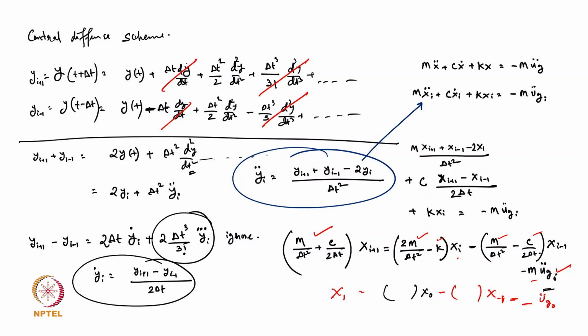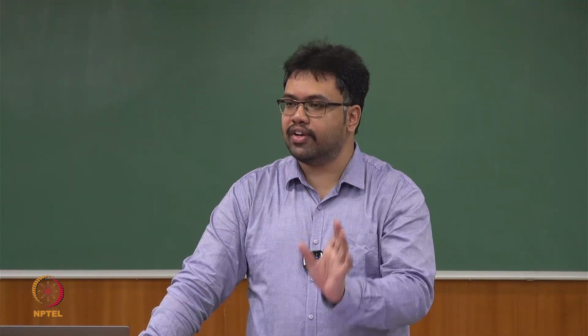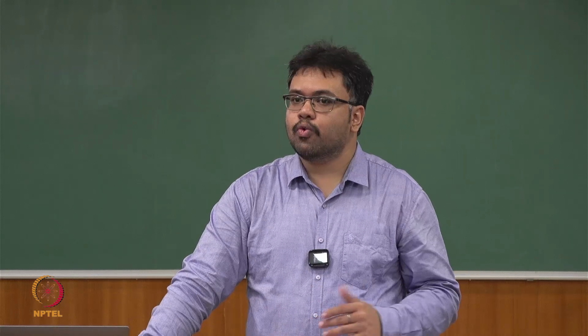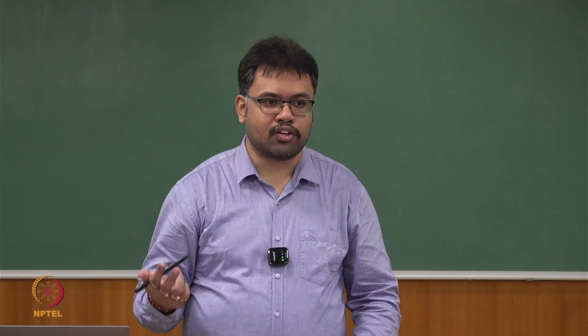Perfect. So that is a very important question actually what he asked. For solving the central difference scheme, we have to give a value for xi-1 also, meaning the x-1 step, which could be the previous of the initial condition. Generally, how can we calculate it? Once we are solving a second order differential equation, in this case we generally have two initial conditions.